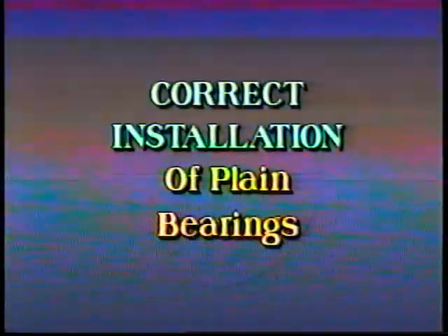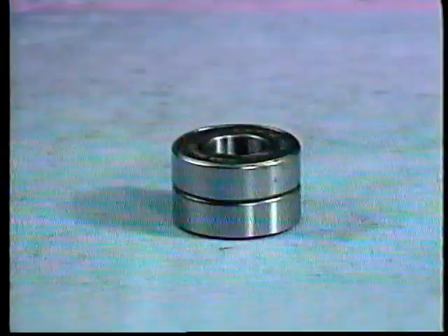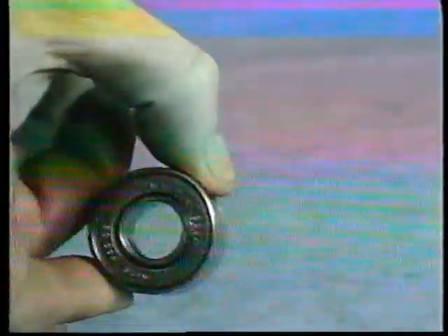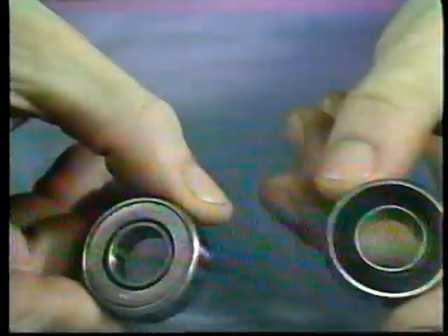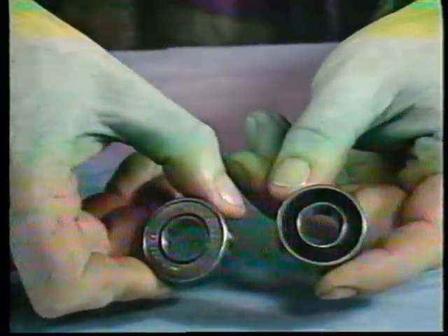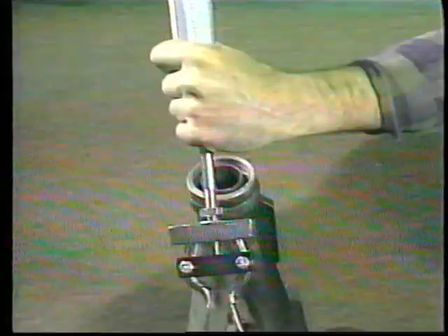You must also make certain that the shaft and bearing diameters match correctly. If a bearing is to be pressed into place, it must fit tightly to ensure full surface contact. Any dirt or burrs or any damage to the bore or the shaft may prevent full contact between the bearing and the shaft.